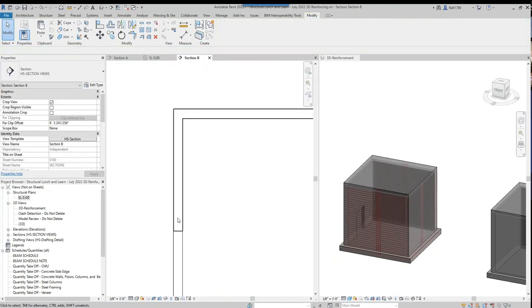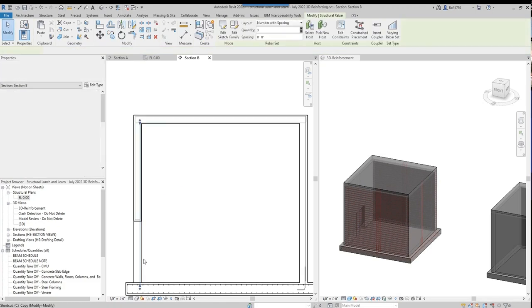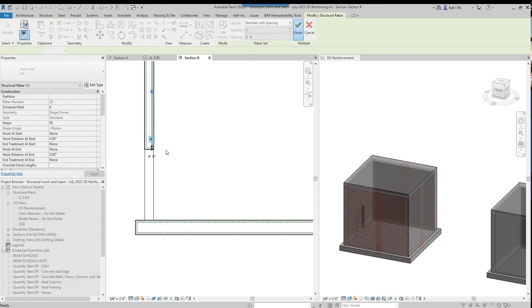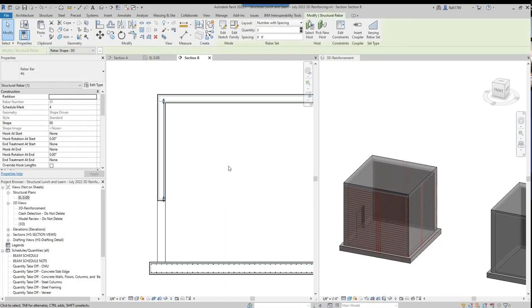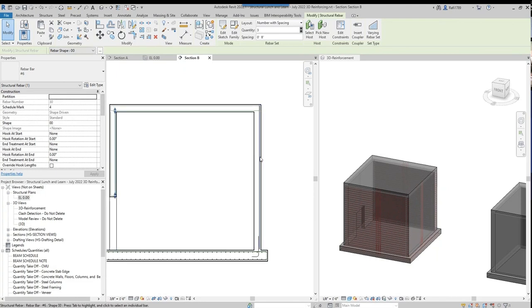I don't want to copy it here because it's not there, but maybe I want to copy this bar here and then edit my constraints so that that's there, right? So the concept is, I don't want people to think that you're modeling rebar in one place and then another place and then another place, constantly doing the same exact functions. Copy, paste, mirror, rotate, whatever you need to do to minimize redoing the exact same thing. And if this is a different size than this one, copy it and then change the size. That's what the colors are for.